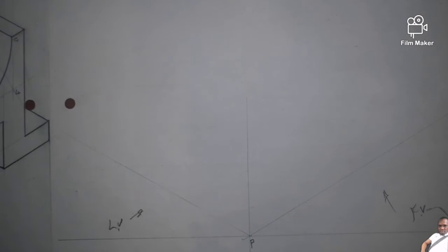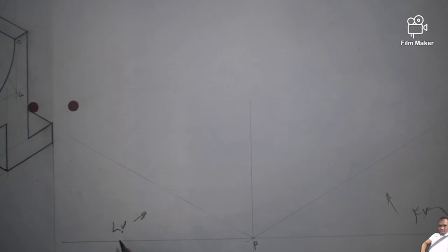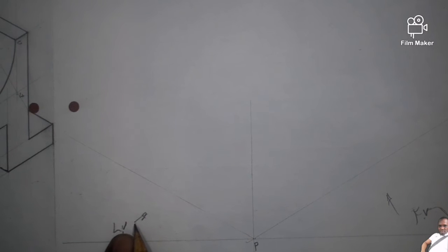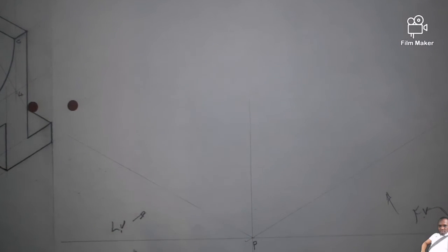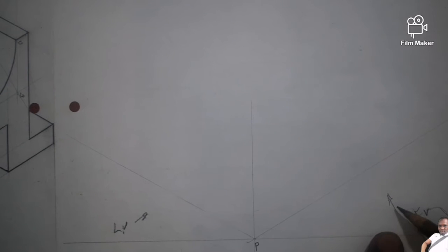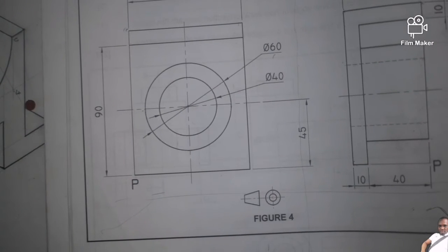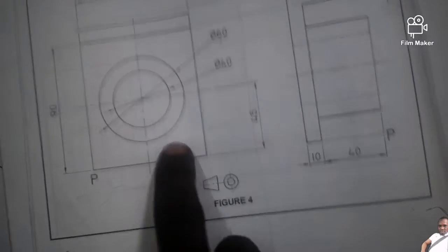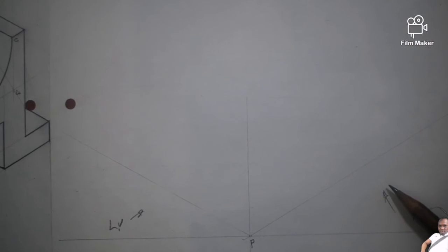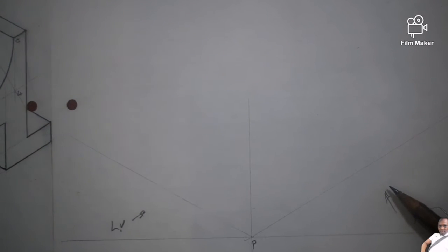But the quadrant scenario here is not applicable. So what I see on my left hand side is what is supposed to be on your left hand side, so that the front view is going to be on your right hand side. If these views were given in third angle orthographic projection, the front view was going to be positioned this side, so that the right view is going to come to your right hand side.